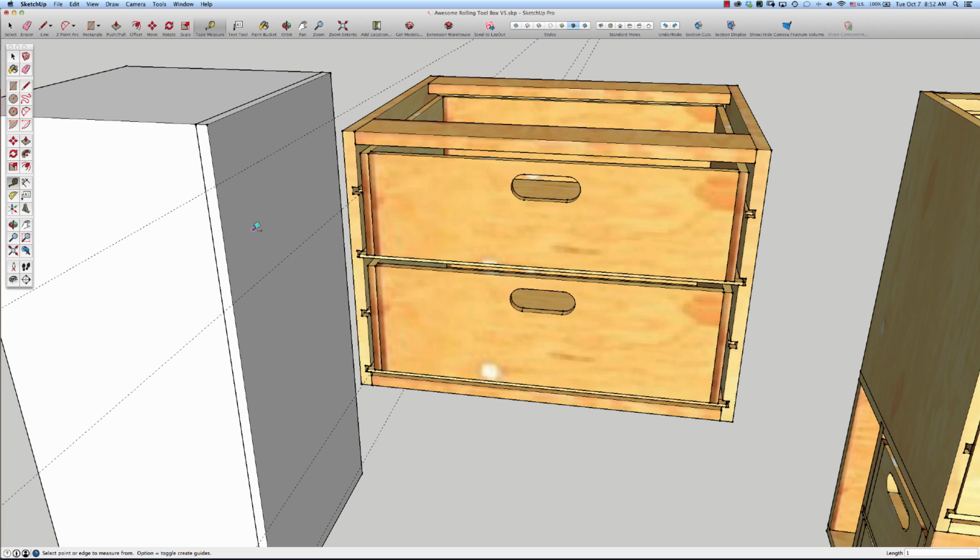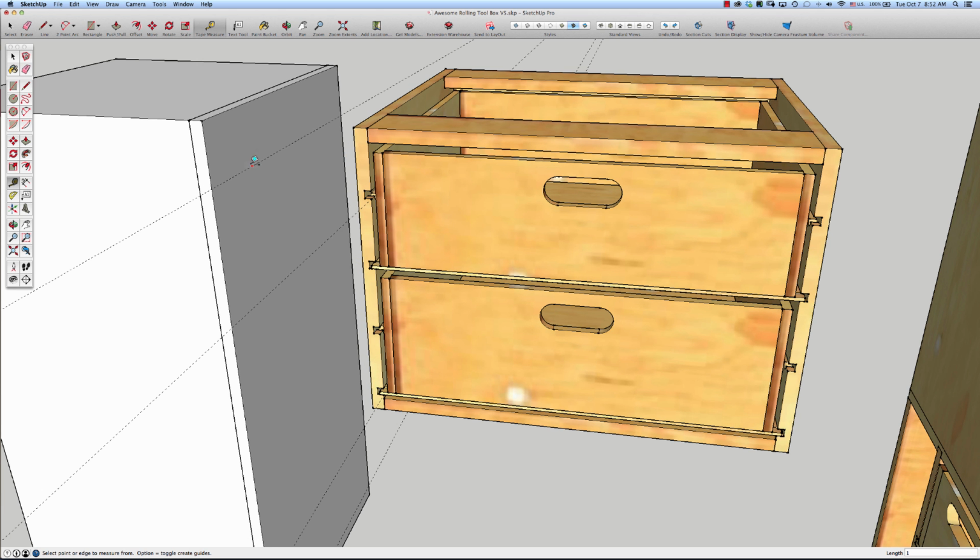All right, I know that these dados are 1/2 inch, that the bases on the drawers are 1/4 inch, and with the detail on the bottom where the screw drops into this notch, I need room for the 1/4 inch to lift up to pull the screw out. So that's where I come up with 1/2 inch. So I'm going to grab this and come up, click, 0.5, enter.